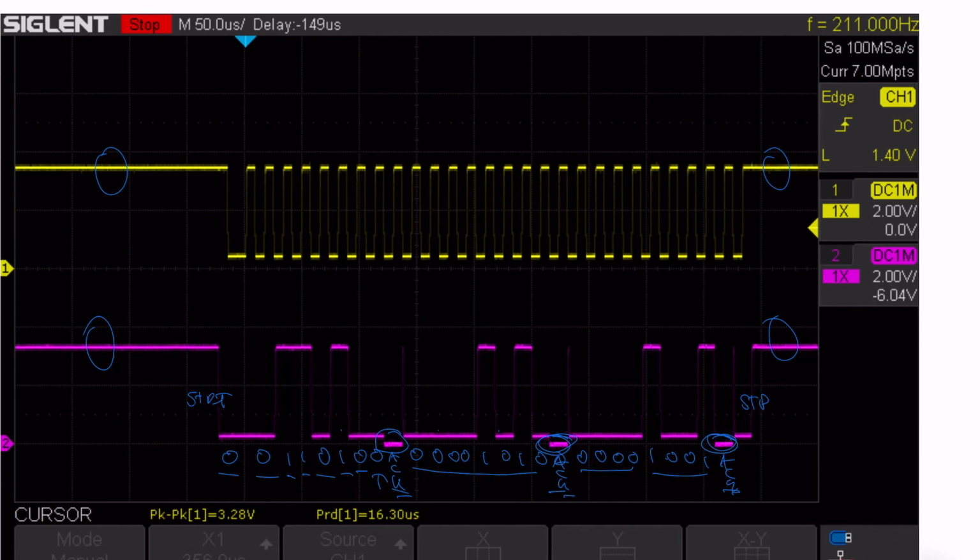One of the best ways you can see this, if you have the opportunity, is to connect your scope to the I2C bus of whatever device you're looking at. Take a credit card and line it up against the rising edge of the clock and see what data value it lines up with. From there, you'll be able to read each individual value. Now, it'd be a lot easier if you had a protocol decode and you could just decode these values in hex or binary. This wraps up the end of the first video of the I2C series, and as the videos progress, we will be adding more detail and going into more specifics.